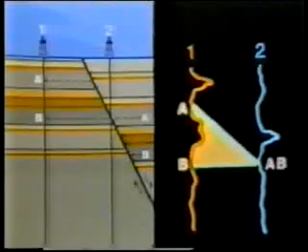If two wells intersect the same strata, but only one encounters a normal fault, a comparison of their well logs may reveal the missing section. The stratigraphic interval, as seen between A and B, is present in the well log on the left and is missing from the log of the normally faulted hole on the right.